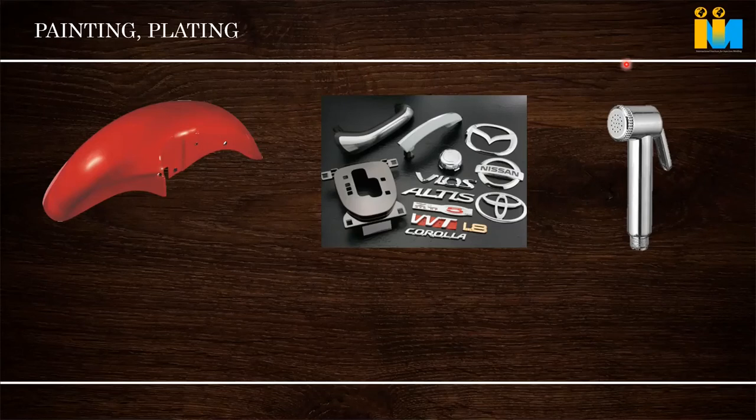So proper gating is needed. I discussed shear rate: when we are doing plating or painting, it should be very low. Normal ABS shear rate could be 50,000, but with this secondary operation there is chemical attack, and the material goes to severe conditions. After painting it has to go to an oven and be cured at some temperature, or sometimes UV attacks it, so it has to be molded at lower shear rate with a better molding process. More care has to be paid. Whenever something secondary is going to happen, we have to take care in the mold and product design. So much care has to be taken. So these are some plating applications.